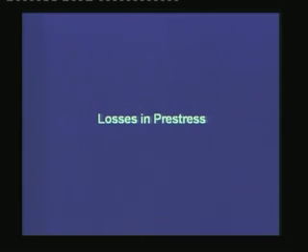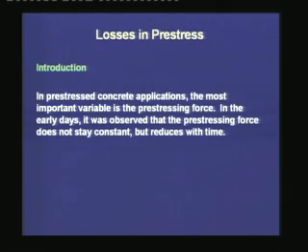Next, we are moving on to the losses in prestress. Unlike a reinforced concrete member, the strength of a prestressed concrete member is not constant throughout its lifetime. Even if we neglect the deterioration, the prestressing force drops with time due to the time dependent losses. Hence, the calculation of the losses is very important in prestressed concrete applications.